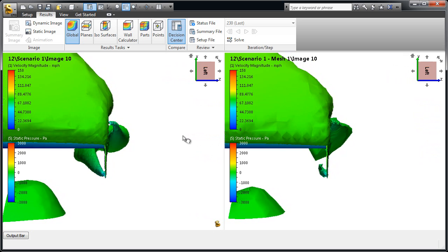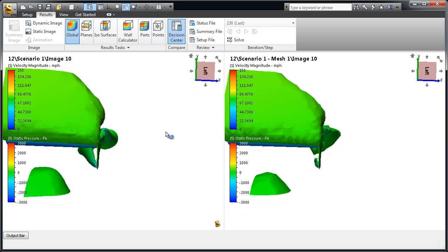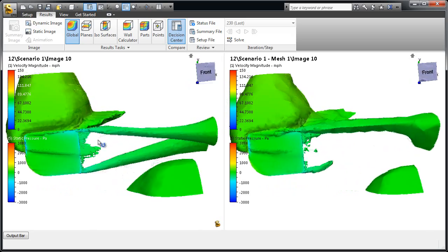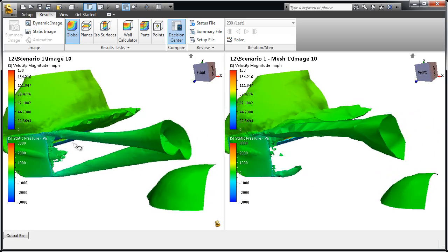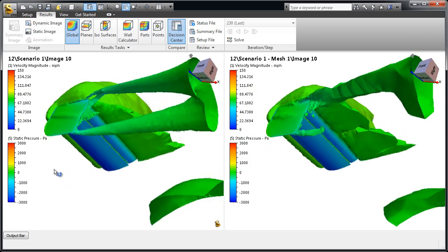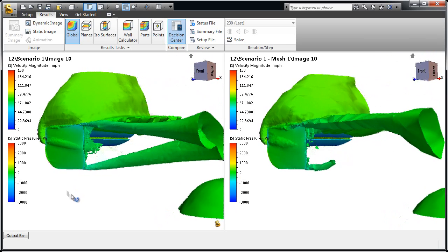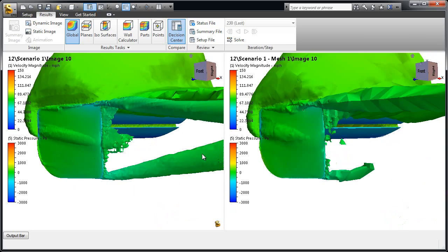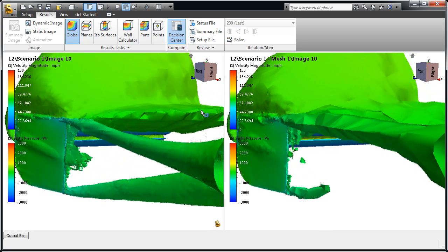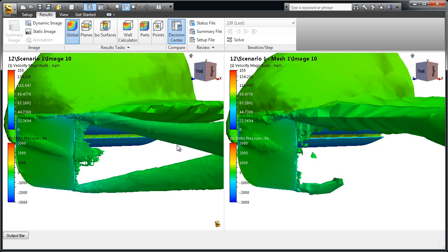An isovelocity surface helps to visualize the two flow disturbances. The low pressure under the wing causes a pressure differential between the free stream air outside the end plate and the air passing under the wing. Air outside the end plate rushes under the end plate as it passes the wing assembly, developing into a large downstream vortex. A similar effect is seen at the top of the end plate, where high pressure air escapes over the edge of the assembly. These two vortices are captured perfectly with mesh adaptation.